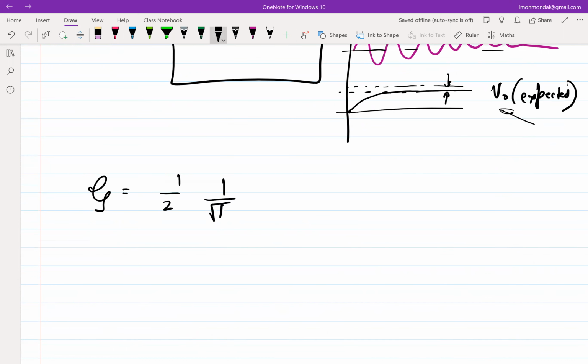So now you kind of get a handle, right? What is the condition of underdamped? Zeta should be less than 1. The critical damping case is when zeta equals 1, so your output settles without any ringing. If zeta has to become 1, then all I have to ensure is that the ratio of P2 and P1 is 4 times the DC gain.